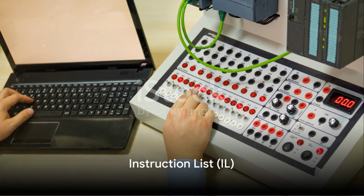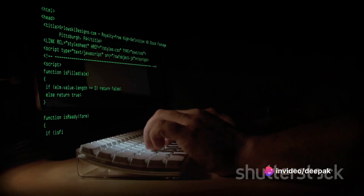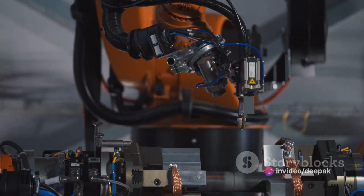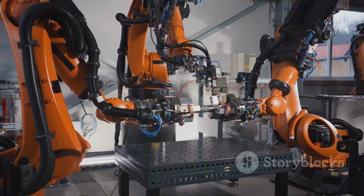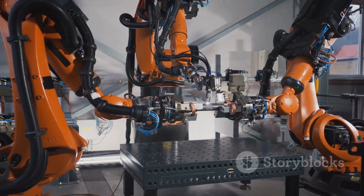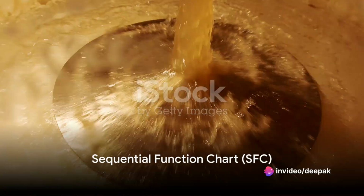Instruction list, or IL, is another PLC programming language that's worth mentioning. It's similar to assembly language in traditional programming and uses simple instructions to control the PLC. Imagine you're programming a robotic arm. Each movement of the arm could be an instruction, with the entire sequence creating the task the arm needs to perform. Finally, we have Sequential Function Chart, or SFC.